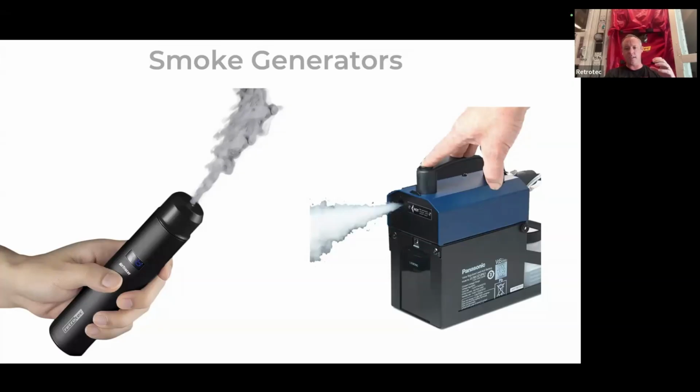Basically, that small handheld fogger is really good just for identifying where the air leak is. You're not going to fill up a duct system with it, and you're not going to fill up a room with it, but you can see how air is interacting with a surface if you have pressure behind it. I'll show you a few different ways of how I use it.